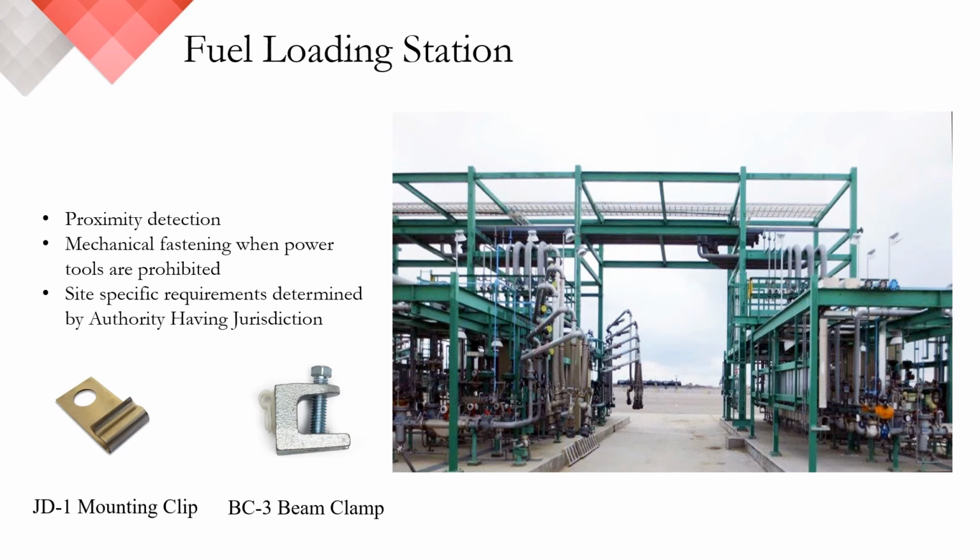And again, I mentioned it before, the 2.5-inch bend radius, and allowing a little slack in between your fasteners so the Protectowire can ebb and flow, so to speak, if it's outside with the seasons, because it's going to constrict and contract whether it be cold or warm. So again, it's just those little things that you don't know if you don't know. And the right mounting fastener can make all the difference.